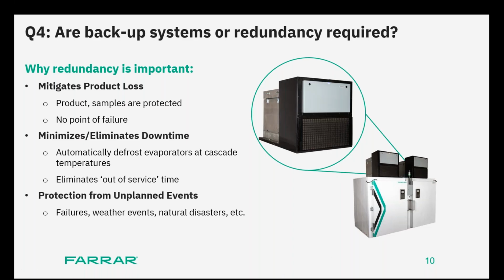You know, that's a great question that you've asked. When it comes to mitigating failures, before we start with day 1, day 2, day 3, before we go down that line, lots of people do not think about putting 100% mechanical redundancy into a system. If you do it from the very get-go with that mindset, it will help out greatly. So what is 100% mechanical redundancy? They are 2 independent, identical systems that each can handle 100% of the load. So each system can do it on its own.